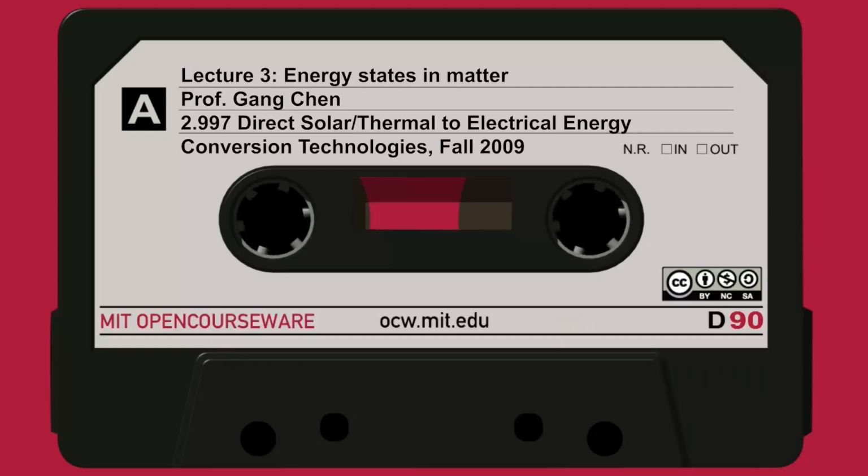And the density of states is a mathematical concept, but it's very convenient. Really, it's the number of quantum states per energy interval. And in the parabolic band, it's a square root relation. Density of states equals square root. And of course, below EC, where EC is at the bottom here, there are no states in this region, in the forbidden band gap. So that's a typical bulk material density of states.